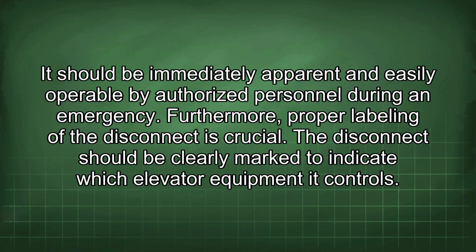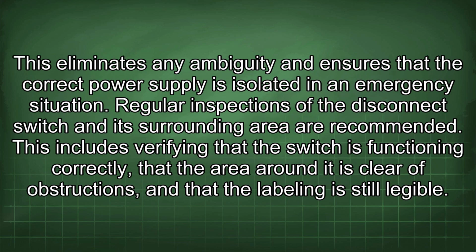Furthermore, proper labeling of the disconnect is crucial. The disconnect should be clearly marked to indicate which elevator equipment it controls. This eliminates any ambiguity and ensures that the correct power supply is isolated in an emergency situation.